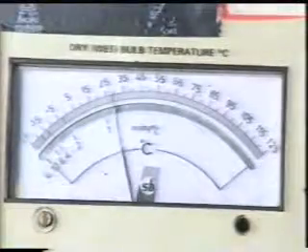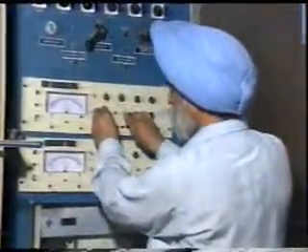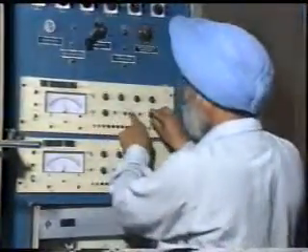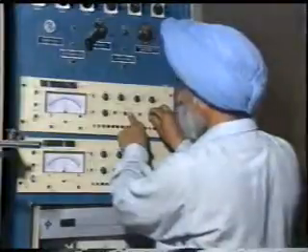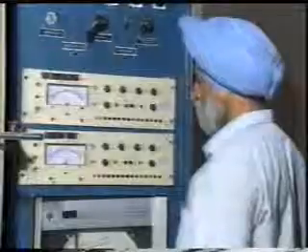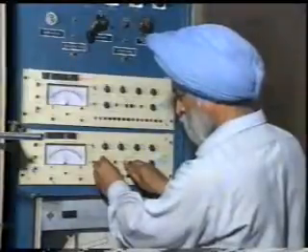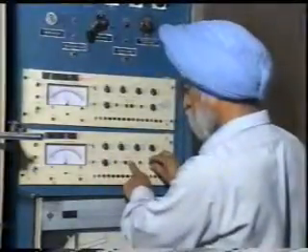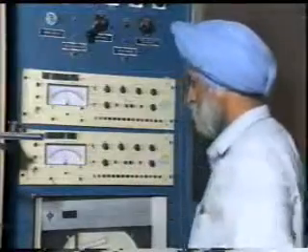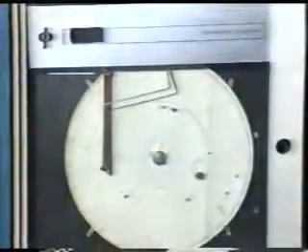The chamber temperature is maintained at 40 plus minus 2 degrees Celsius and with a relative humidity of 93 plus minus 2%. The equipment is kept under test conditions for 4, 10, 21 or 56 days depending on relevant specifications. The record of chamber conditions is taken on a graph.